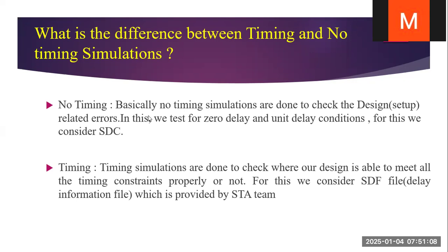No timing simulations are done to check the design setup related errors. In this, we test for zero delay and unit delay conditions. For this, we consider the SDC, Synopsys Design Constraints file.